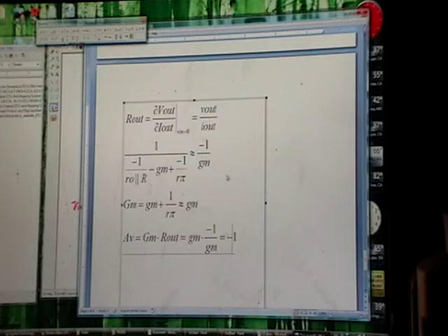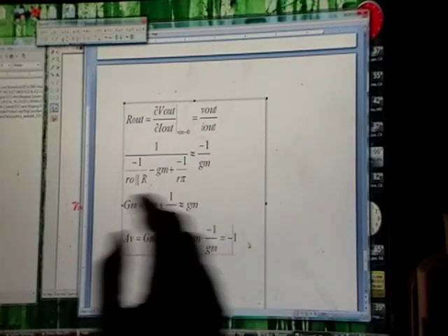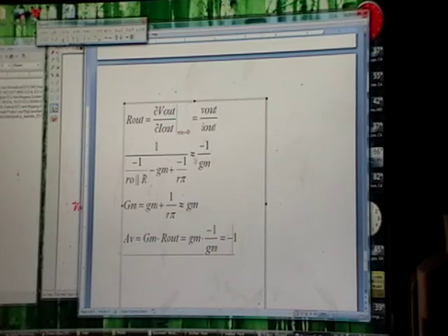And the other thing that you notice is 1 over GM. If GM is 0.2, then now R out is like 5 ohms. Okay? And that's what you want. You want a really low R out. So the good thing about this follower is it gives you the same signal in, since the gain is 1, gives you the same signal out as in. Might be shifted a little bit, but it gives you the same signal out as it receives. But it shows a very large R out.